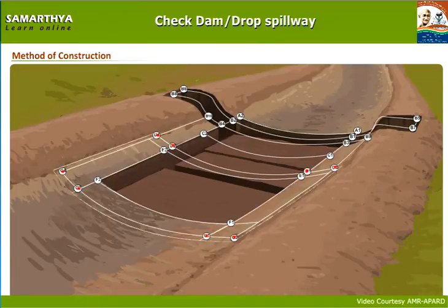Mark at 0.15 meter on both sides of D1, D3, G3, G1, F1, F2, G2, G1, G2, G4, D4, D2 with lime powder.